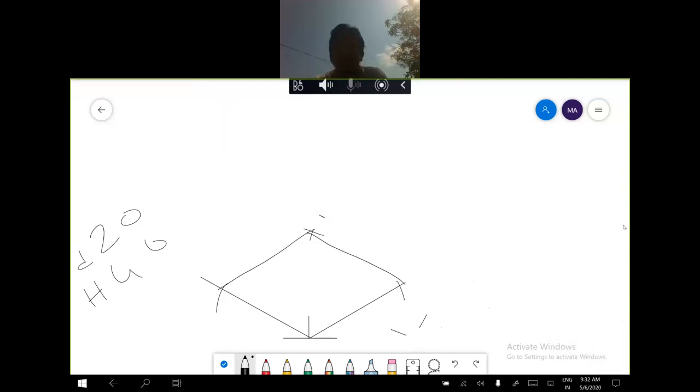After constructing this, using the 4 center method, I'm drawing the circle here. This one is 30 degrees, this one is 30. With the given diameter, I have constructed a square with sides 20, 20, 20. After that, I am marking the center at 10, 10, 10. After that, I join from the top vertex to here, bottom vertex to here. These are all construction lines.